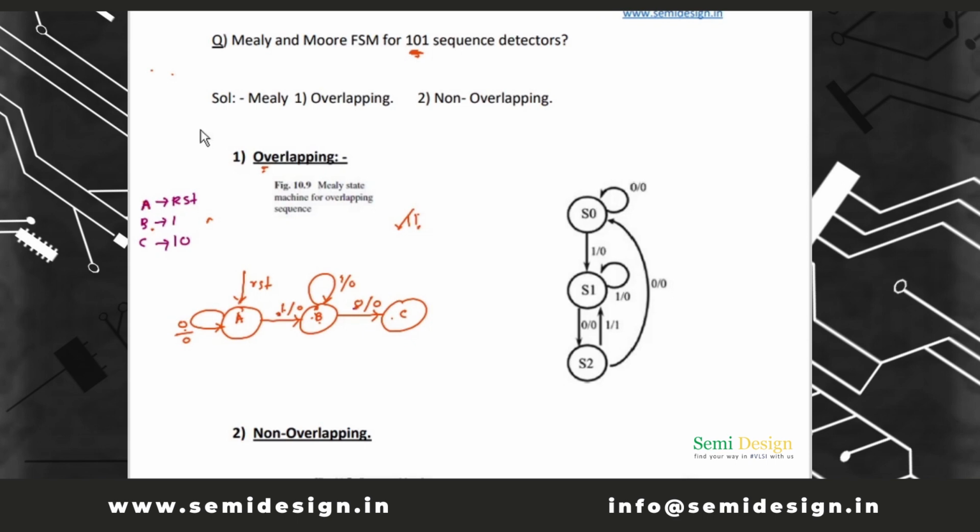Now at C state, this 1, this 0. Okay, this 1 0, and if we take 0 here at C state, now discard this first bit, compare this 0 0 with this table. Nothing is here, right? 0 0. Discard another bit, compare this 0. 0 is here, no. Discard this 0 also, and nothing is there, so it will go to initial state, reset state, when 0 is here, and output is 0 because sequence is not detected.